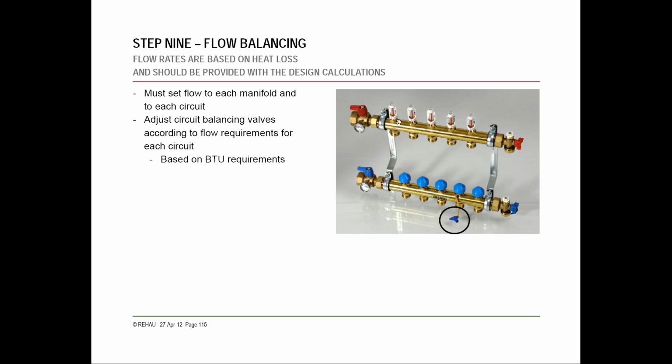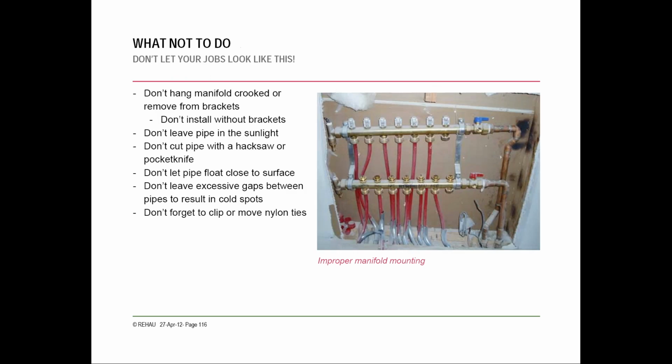You could be making your manifolds custom with copper, using another manufacturer. Same basic rules apply. You want to make sure you're balancing based on what your design was, so that you're not running an absurd amount of water through some loops and not enough through others.